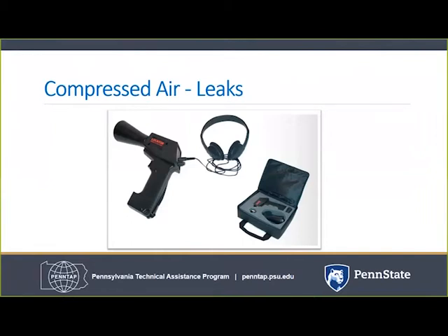First, establish your compressed air usage baseline. Then, estimate the volume and cost of your leak losses. This will give you a rough idea of the potential for savings. Next, identify and document leaks. After that, prioritize and carry out leak repairs. Then compare your improved performance against your baseline. How much of the potential savings have you realized? Then repeat this process.